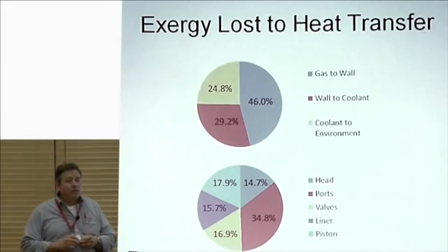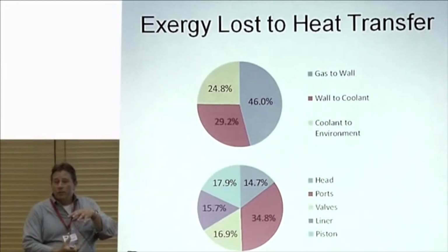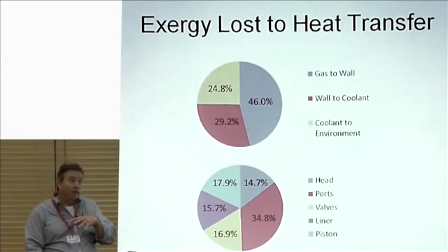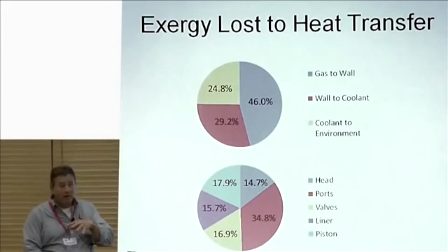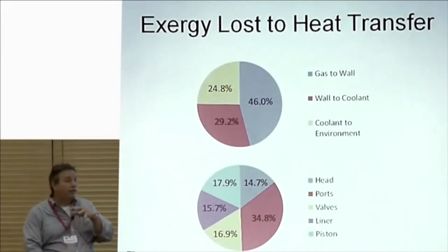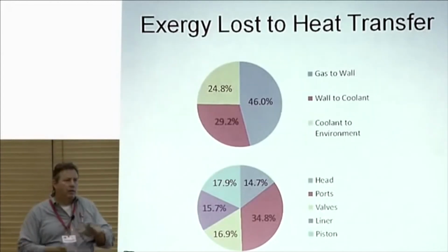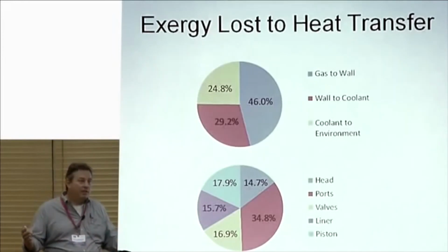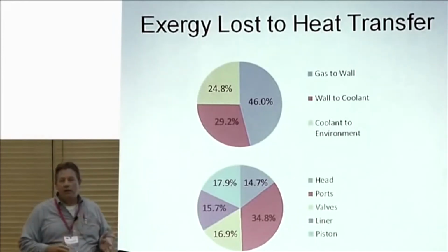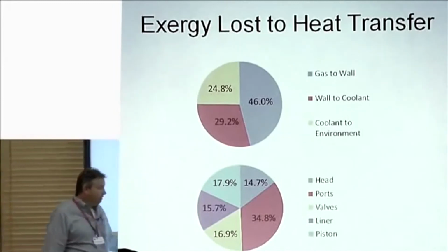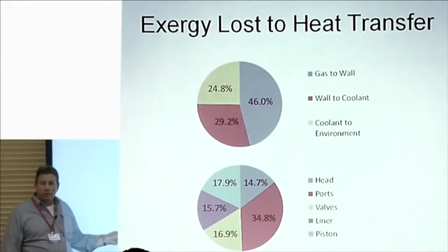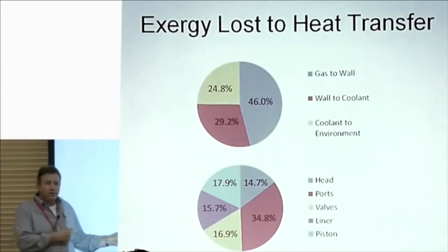But one of the really tricky parts about this was handling the interface between the piston, the rings, and the liner. If you're going to make that out of ceramic, you now have a really tough problem because the temperatures are really high, not conventional oils. So you're talking about solid lubricants, really tricky things, and funny rings, really, really hard. Okay, but I've never been one to go after 100% of something. I'm always the simple bet: give me half. If you look at this, it suggests leave the liner alone. Go after the valves, the head, the piston, the ports, and use conventional rings, conventional cooling, conventional lubrication down on the bottom end.